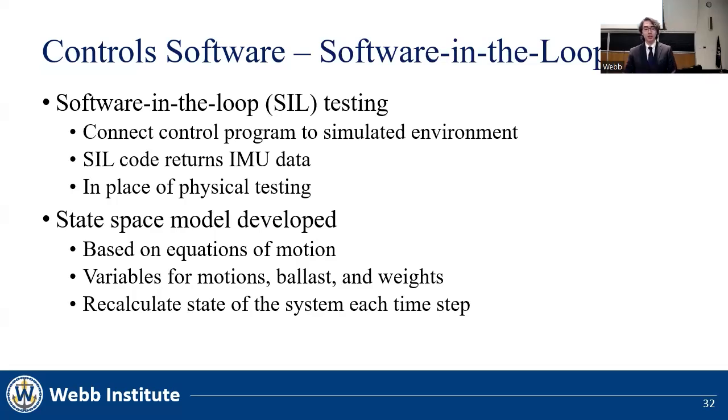To rapidly test our controls software out of the water, we developed a software in the loop, or SIL, code in Python. This used a simplified model of the glider to test different controls functions.